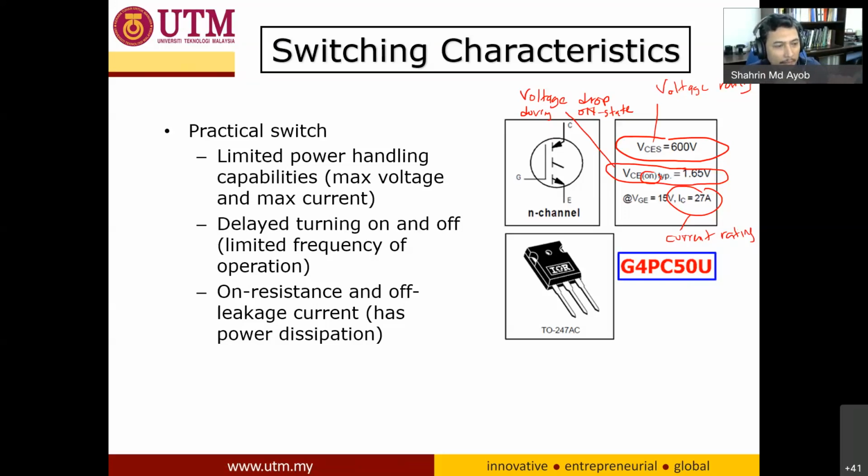Actually, the size of the cable will determine what is the maximum current that can flow. If I use this cable, and the current that will flow inside this one is 1 kiloampere, this cable cannot handle that, because the core here, which uses copper, is not thick enough to handle that high current. So my cable will burn out very quickly. If I want to use 1 kiloampere current, I need to use maybe a larger cable.